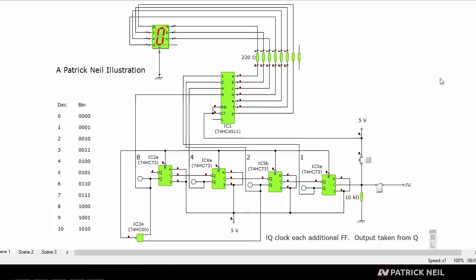Now, just as before, by using the output of one flip-flop to drive the input of the other, we can generate this sequence of signals here in binary. This circuit is a little different from the others because it resets itself whenever the code for 10 is present on the output. This detection is done by using this NAND gate to detect whenever the code for 10 is present, which means this goes high and this goes high. You can see it here. This is the code for 10: low, high, low, high. We should have a high here and a high here. And whenever we have 2 highs, the output will go low. Now this low will reset the flip-flops back to 0.